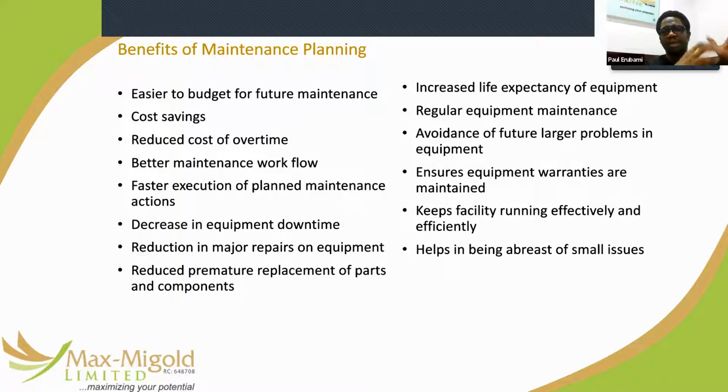But if you did not have a maintenance plan that shows alignment with what the manufacturer has prescribed, the manufacturer can easily put the blame on you for that defect and end up not taking care of your warranty or reimbursing you for loss at that time because you did not create a maintenance plan. But you can say, oh, well, we are doing everything you said in the manual, we're doing it very well. You need the maintenance plan and the record of the maintenance to prove that you're actually doing it.